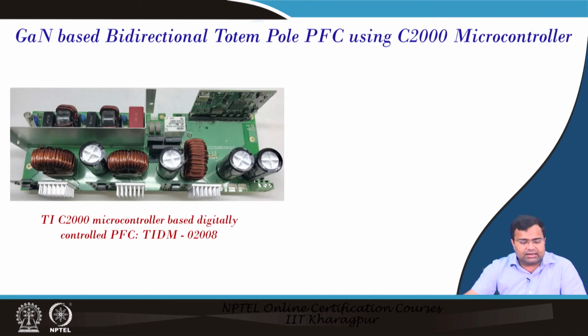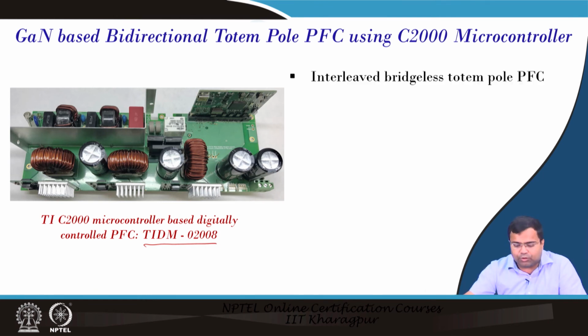Another solution is a GaN based bidirectional totem pole PFC using the Texas Instruments C2000 series microcontroller. In fact, this reference design will be demonstrated particularly as an example case study, because we will be considering how to implement digital control using the C2000 series microcontroller. So, one case study at the end will be this particular reference design of GaN based totem pole PFC.